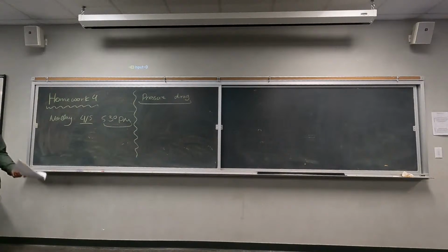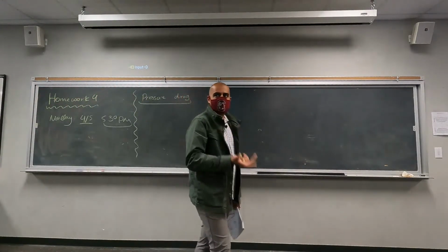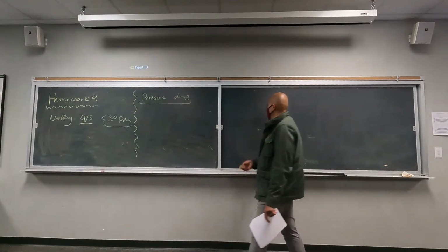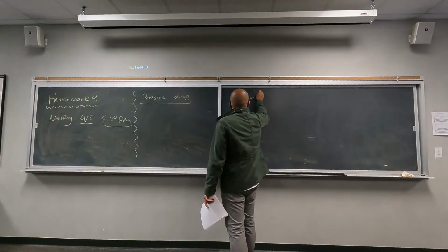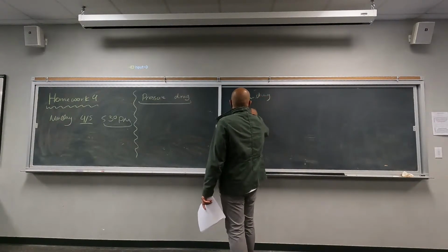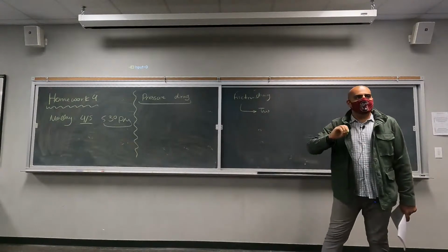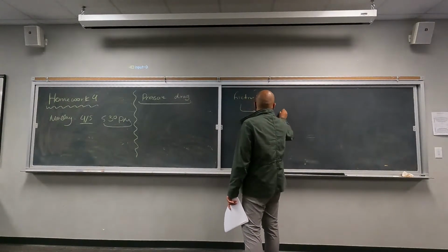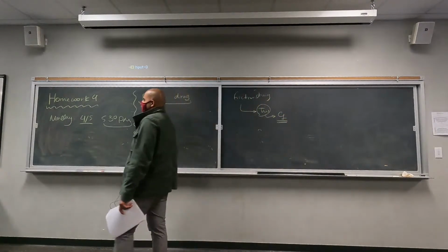We want to talk about the pressure drag. We have already talked about the friction drag. Friction drag is there because of the shear stress between the wall, or the airfoil. We actually calculate the friction coefficient. We don't really calculate the shear stress at the wall.